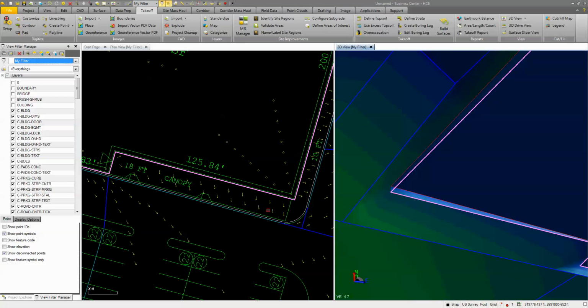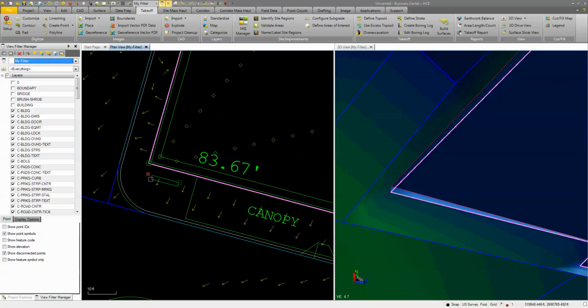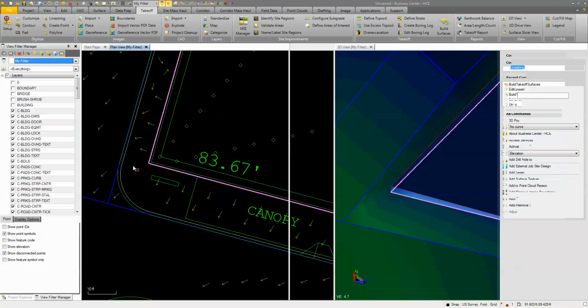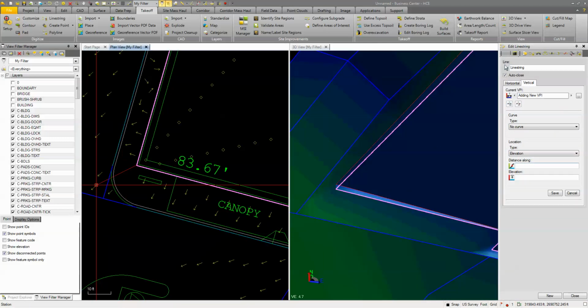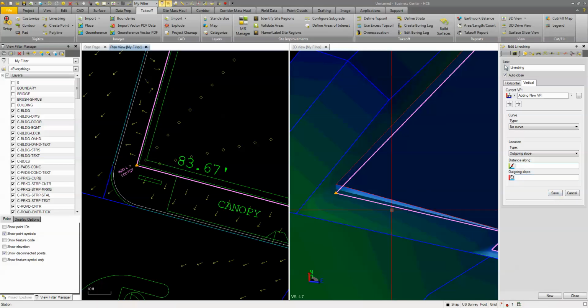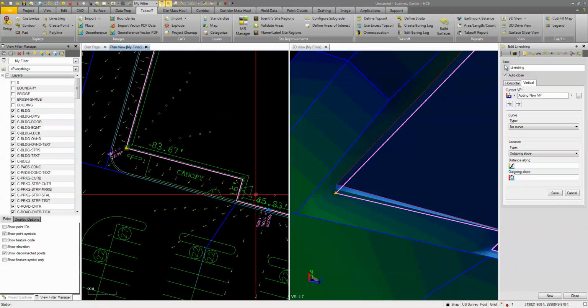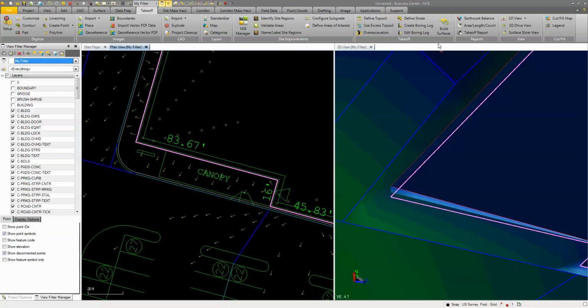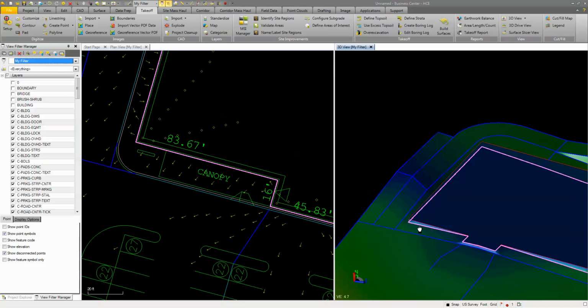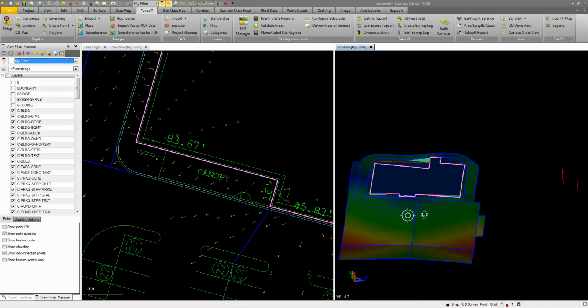We might do the same thing over on this side, where we make sure that this point, all right, so just checking our horizontal, we're coming in this way. Our vertical, we're going to go that way. So our outgoing slope in this case is going to be 1%. It'll adjust that down a little bit as well. Okay. So again, just adjusting, tweaking, rebuilding. It gives us our general planes. We've got our building, we've got our ADA, we've got our parking.